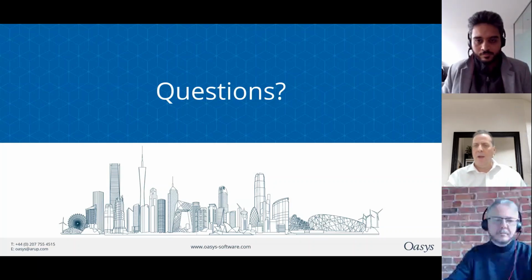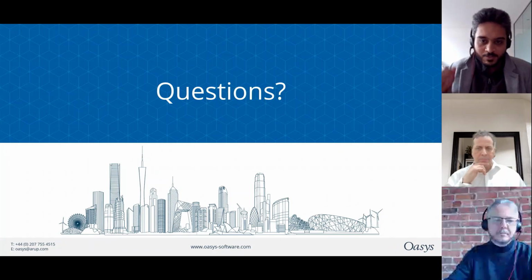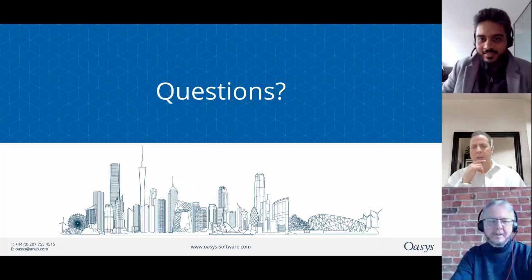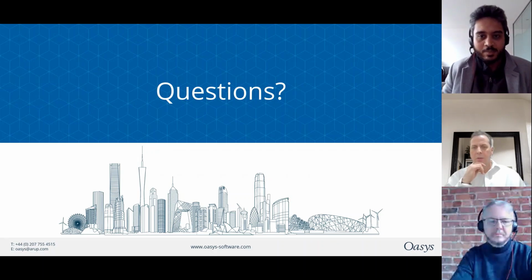Right, somebody's asking where they get the Grasshopper plugin from. Yeah, so you can get the plugin. I think this was answered before, that you first need GSA to be able to run the GSA Grasshopper plugin, and you need at least build 10.1.60 and above. And once you have this, you can get the Grasshopper plugin from Rhino itself.